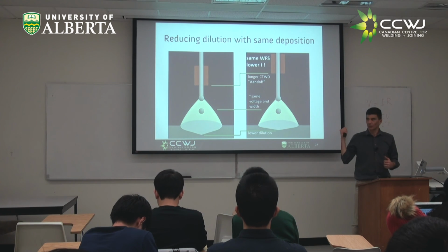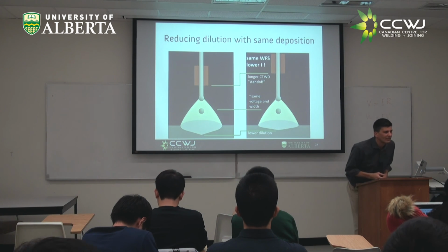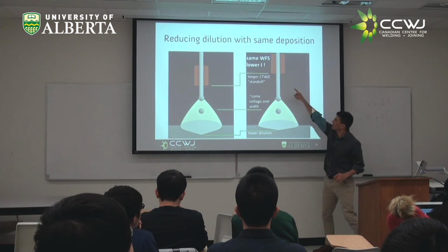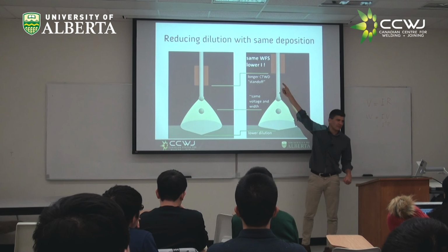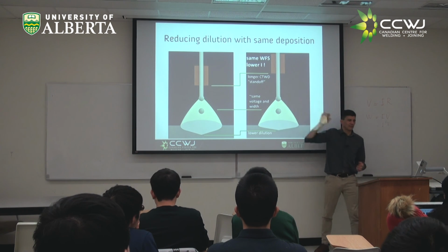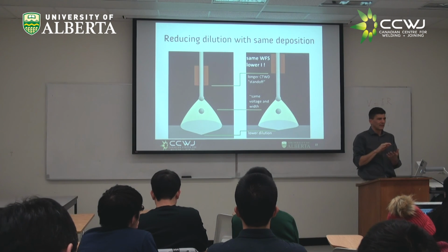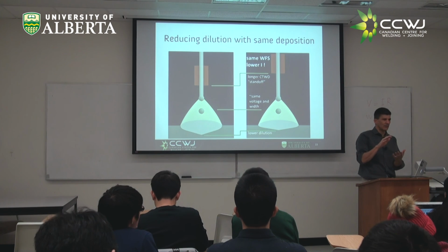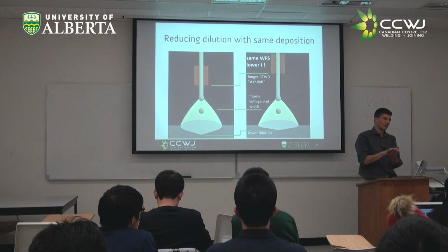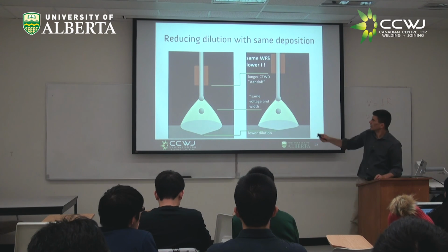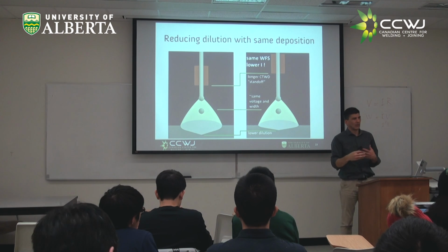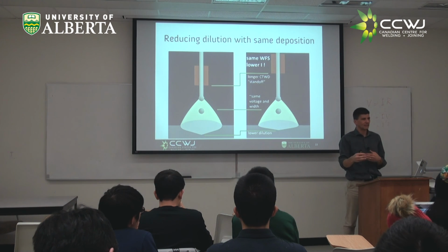I think this is pretty cool. This is a real case. What was the first option? The first option is to increase the contact tip to workpiece distance, the standoff. So lower the current. If you do that and you keep more or less the same voltage, the current is lower because the electrode stickout is longer, and you have all the energy from joule heating.